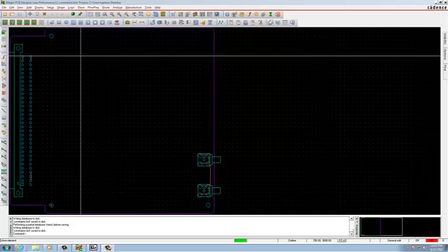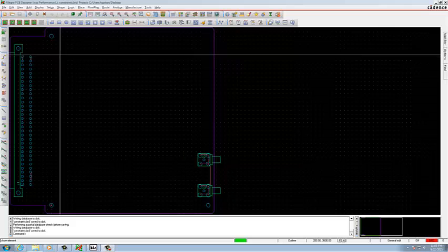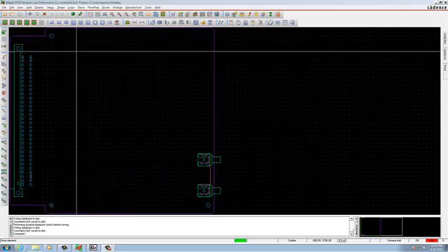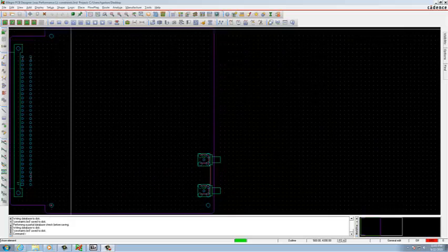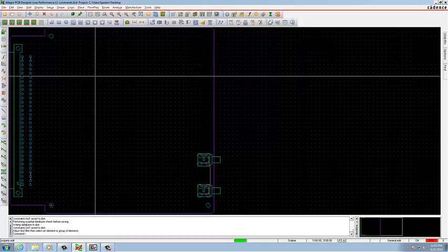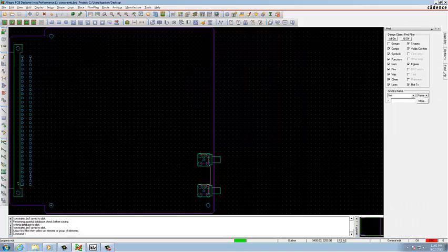Alrighty. So now getting started, what we want to do back in the PCB Editor, just want to click on Edit. Oh, make sure you still have your Constraints file up too. That's very important, because without it, we're going to be doing this for no reason. So just want to hit Edit. We want to click on the properties here. Now we want to scroll over to the Find option on the right hand side. And then the Find by Name, we want to change that to Comp or Pin. And then now we want to click J1. Then we're going to press the Tab key and watch what happens.